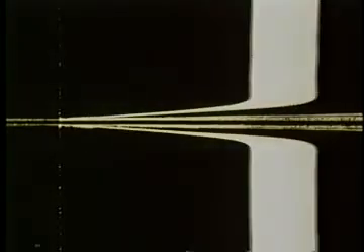We have seen the behavior of two-dimensional boundary layers on a flat plate in a uniform velocity field. So far, the pressure gradients in the flow direction have been negligibly small. However, in most flow situations, there are regions of decreasing pressure and regions of increasing pressure in the flow direction. We will examine these two flow situations separately. First, the case of a decreasing pressure or favorable pressure gradient in the flow direction.